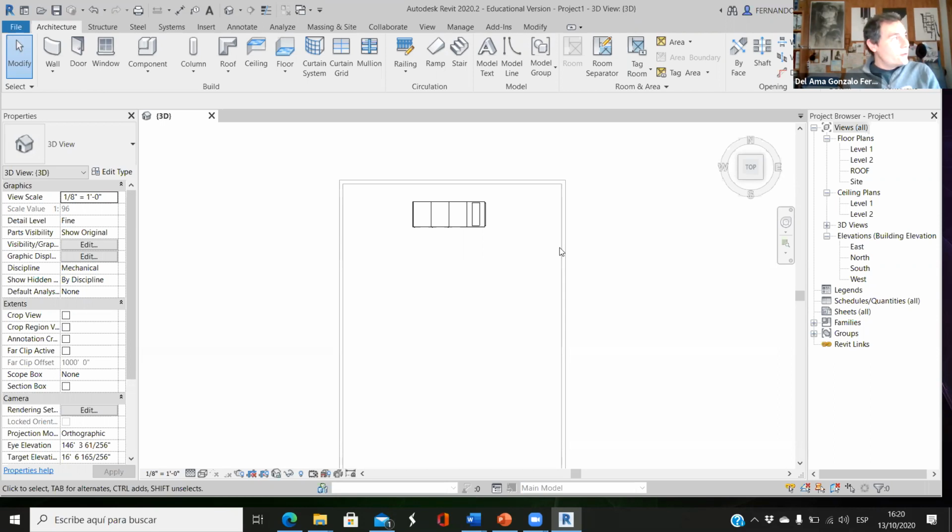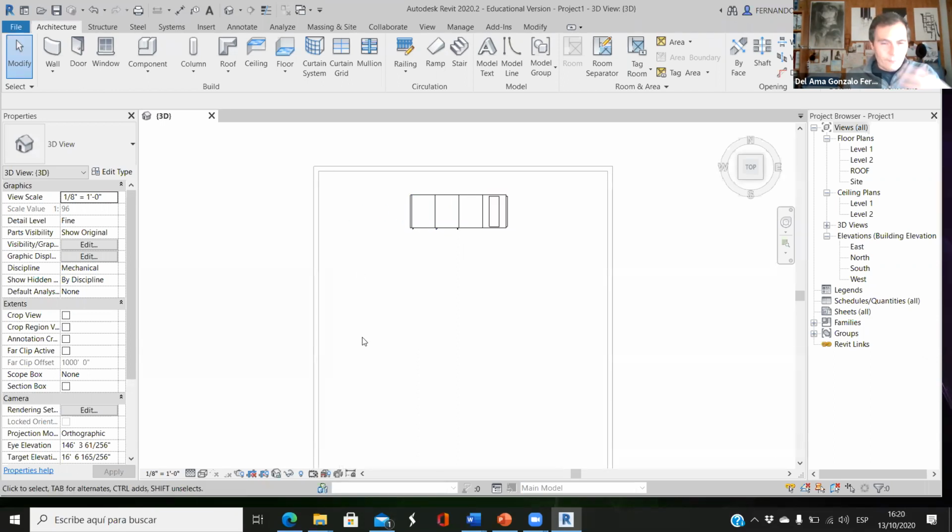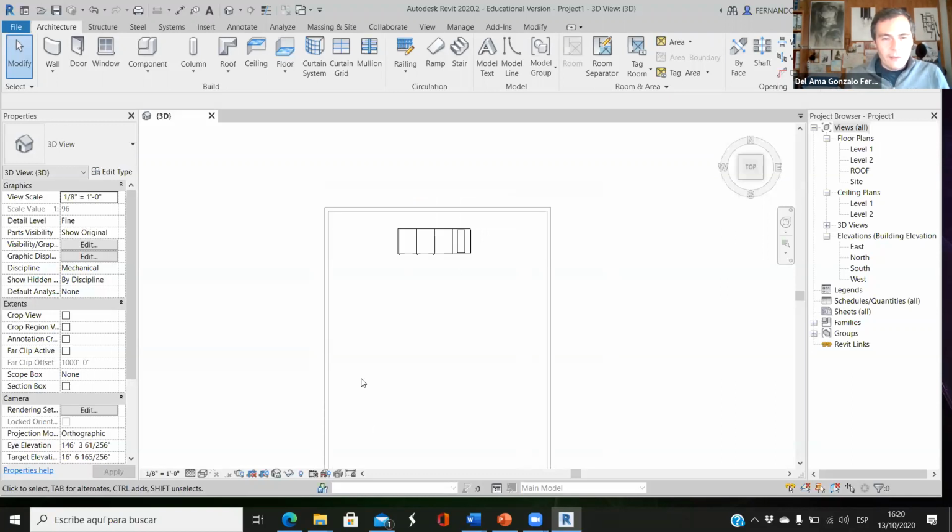Because if things are not well connected, then the airflow will change or will be zero in one of the ducts. And that means that there's something wrong with the connections. So today we will do it again very quickly, but applying the right sizes so that when we check this, it will be correct. Because last time we did the duct work, and then we checked the air velocity, and we found out that it wasn't correct. Today, we will start thinking about the right size, and then we will model with the right size, and the velocity will be the right one.